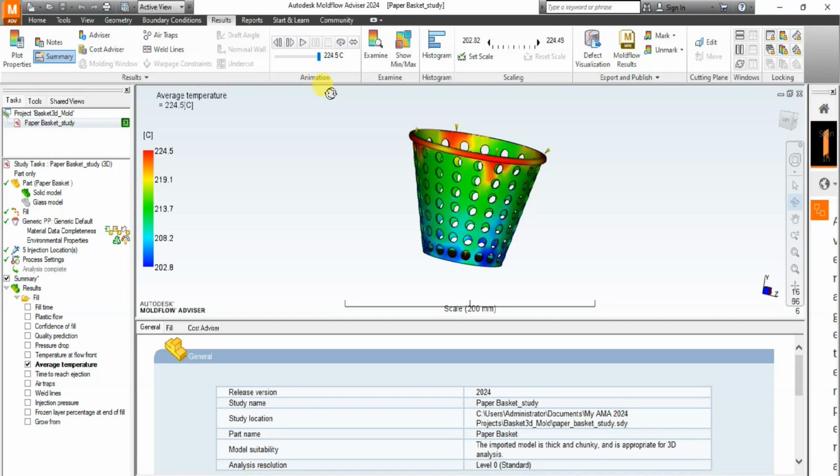Now, for the temperature, for instance, if the temperature is too low, increase the melt temperature. The possible problems that might come from this might be increased cycle time. It might cause material degradation. It can also make the temperature stagnant. Keep it within the temperature limit specified in the material information in the database. Now the other thing is increasing the mold temperatures. You may increase cycle time.